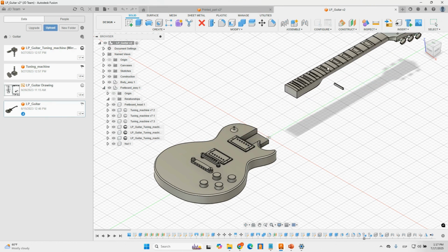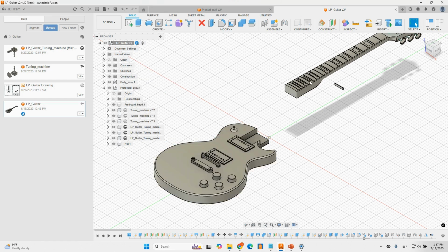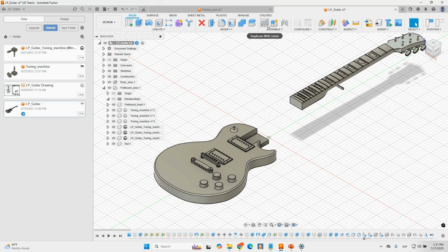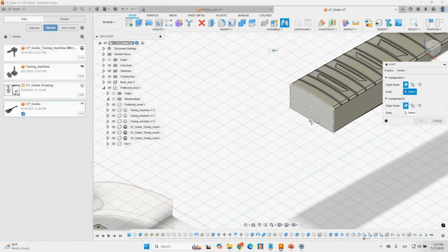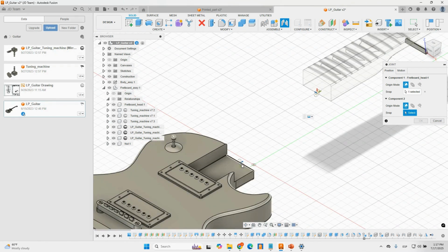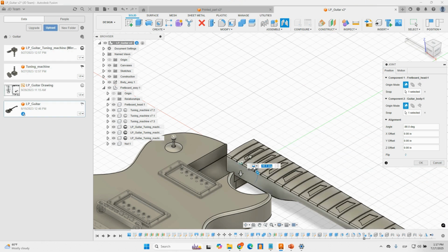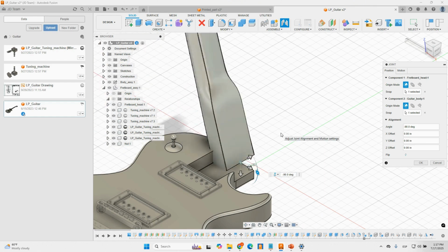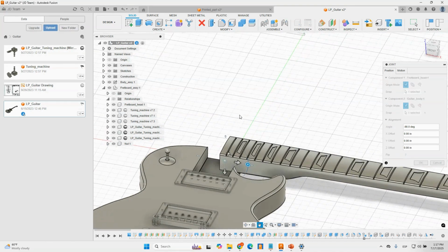basically, I'm gonna go ahead and ground this guy. Parent, there we go. You remember that when you are going to include joints on Fusion, basically you needed to specify the type of movement that you want between each part, right? For example, this edge on that edge right here. Okay, and then you specify the type of joint that you want to create, right? And in a general sense, that's going to be great if you're going to think about creating mechanisms or doing those kind of things.